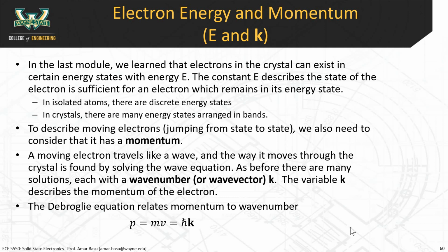They become bands. They call it band formation or band splitting. It causes the energy bands to split up with very small gaps in energy. So electrons can move about those energy bands because there are all these energy states at energy levels very, very close together. So it's easy for the electron to jump from one energy state to the next.